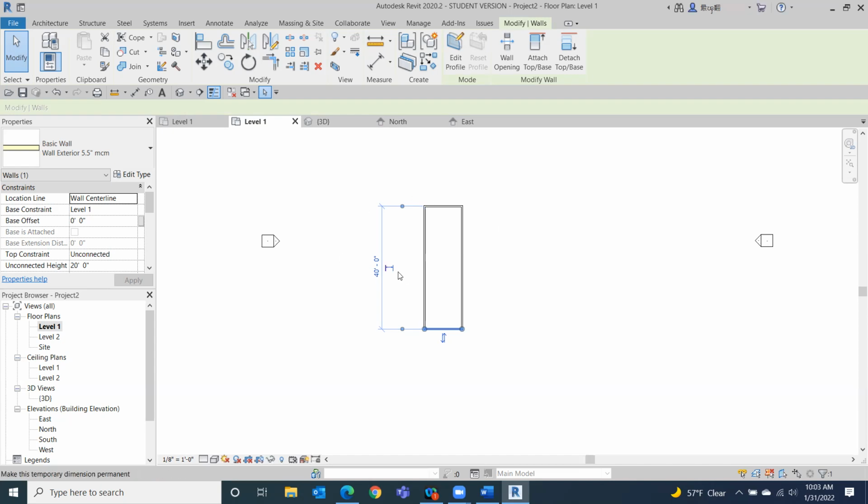So here I'm going to change the dimension. Doesn't matter which side I do it from here because it's just a regular square rectangular building. If I want to change the dimension, I click on the dimension there. Let's make this 15 foot 7 inches, 15 space 7. And notice this wall moved up. That is a big difference when you're looking at stuff. So since I made this wall active, this is the wall that's going to move.